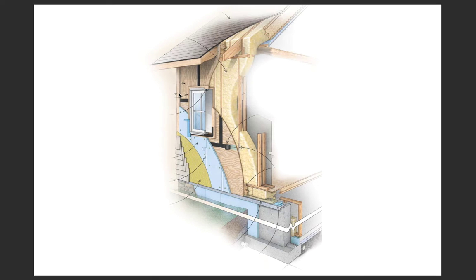Because the demand for having a controlled temperature on the inside, and therefore introducing insulation within our construction, has an implication on how not just heat is transmitted through these walls, but also on how vapor is transmitted through these constructions. We will have a look at this in another video on how moisture control works. But because there's a heat transmission happening, it also means that there's vapor flowing through the construction, and you have to be really, really careful in how that's being assembled.